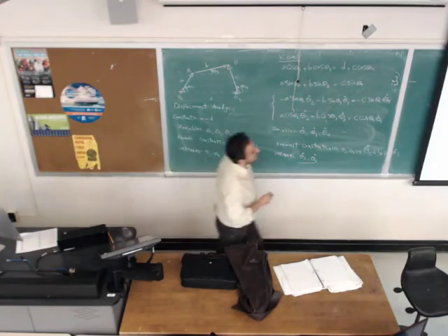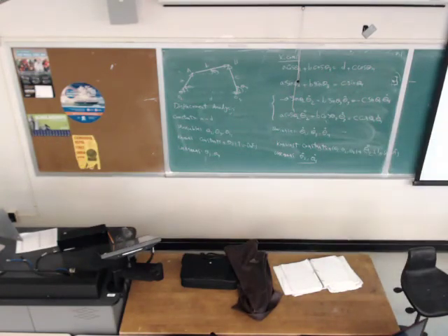We are given the velocity analysis of a 4-bar mechanism. The 4-bar mechanism has the lengths A, B, C, and D. All are given. When the input link is at the angle of 57, the angular velocity of link 2 is 10 radian per second. It doesn't say clockwise or counterclockwise, and since it's positive, it means counterclockwise. So we use positive 10.